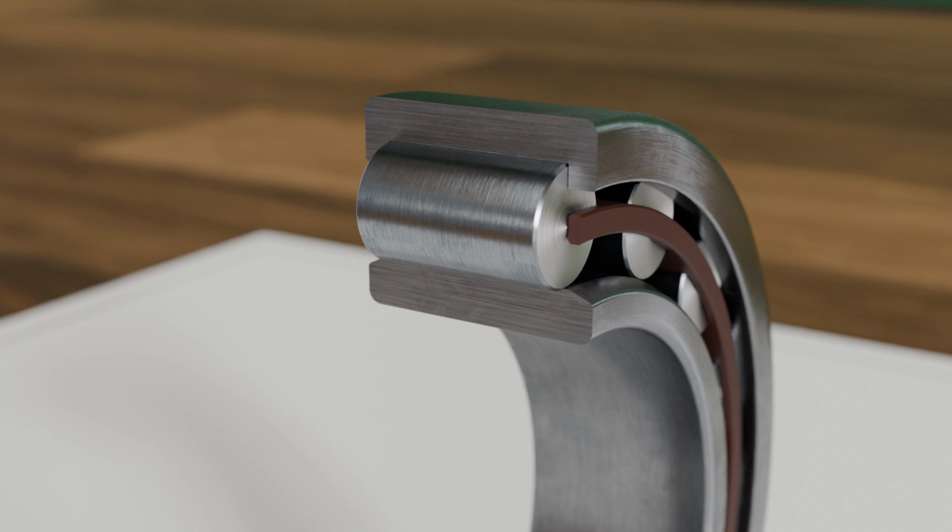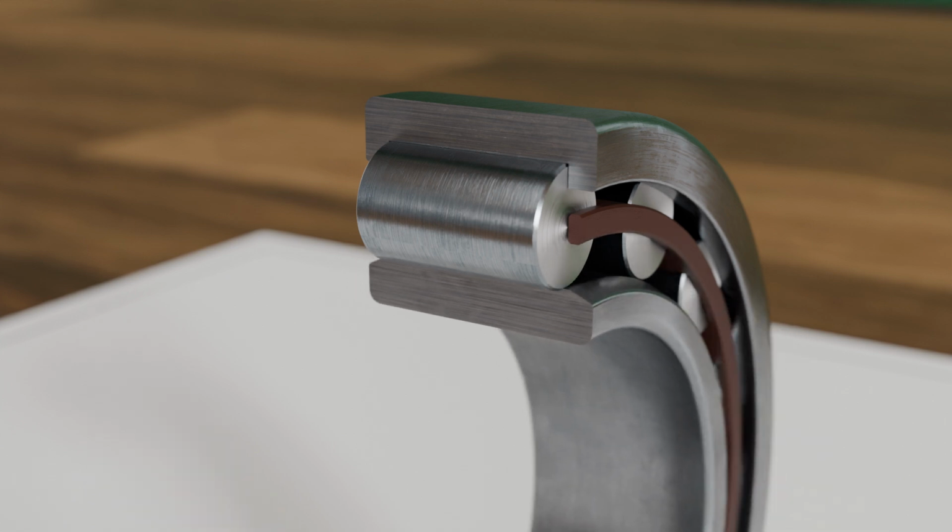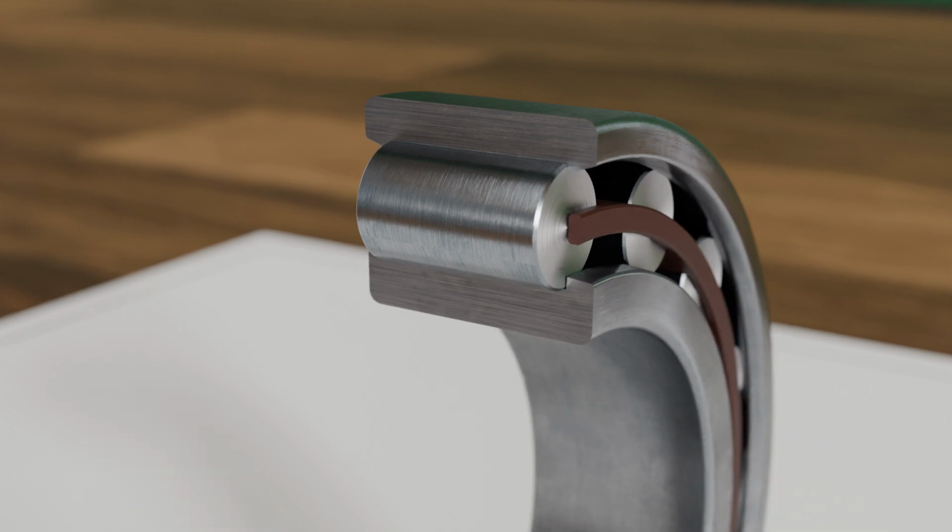However, compared to ball bearings, roller bearings are more sensitive to misalignment and can only absorb limited or no axial loads. For the cylindrical roller bearing variant NU, only the outer ring has flanges between which the rollers are guided. The inner ring, however, has no flanges and can move axially. In the variant N, the situation is reversed. Only the inner ring has flanges, while the outer ring has none. Both variants, N and NU, cannot absorb axial forces. However, assembly is much easier because the shaft or housing only needs to be slid through the other bearing half, once one half is already mounted.